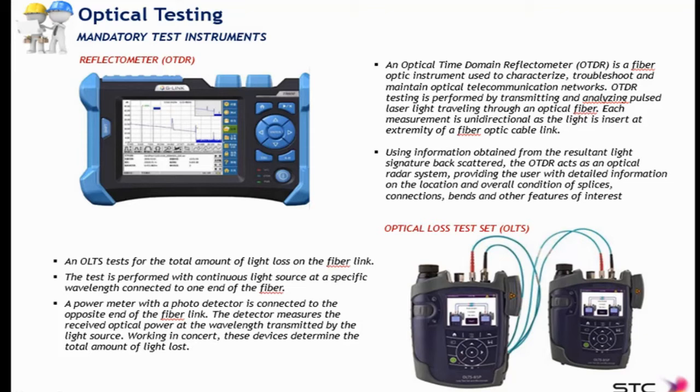The OTDR provides readings on the type of events, insertion loss, and distance. Events such as connectors, splices, or any type of bends are detected by the OTDR and shown on the screen with an estimated value of their amplitude and distance from the OTDR.